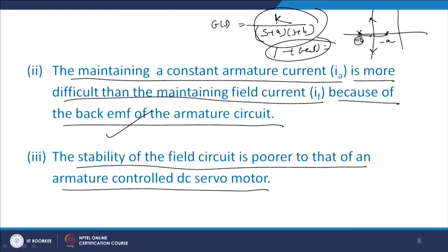So, for second order system the root locus is like this, that is k equals 0 here and k equals infinity here. One root locus starts from here and moves like this, the other root locus moves like this. This is the imaginary axis, and we see that if the roots are lying on the right side of the S plane, the system is always unstable; on the left hand side the system is stable.